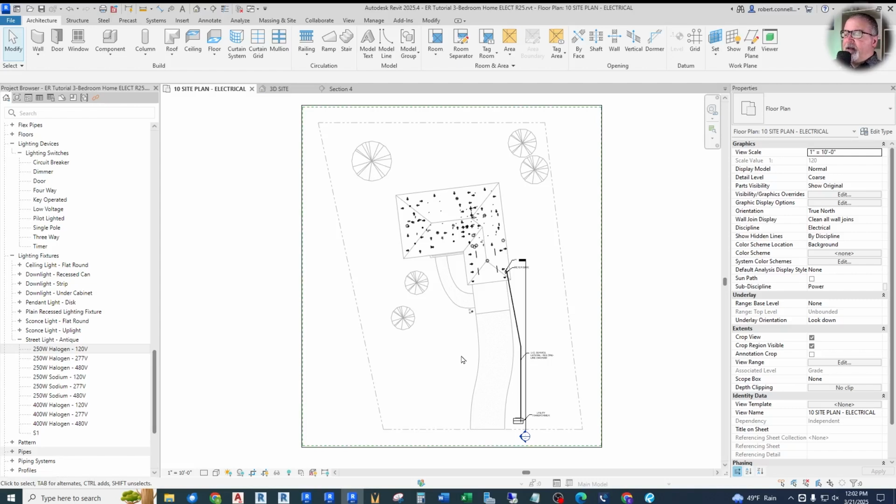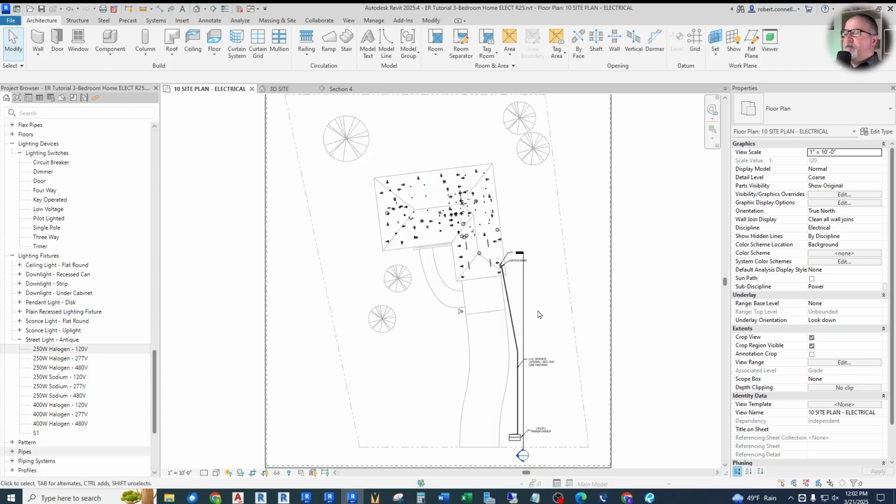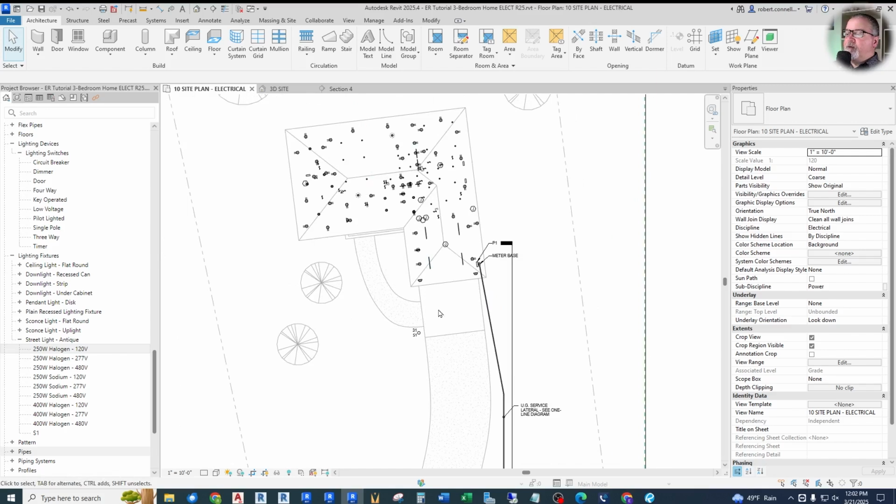Now to deal with this filtering issue. All right, hang in here with me. Filters are a little advanced, but they're very important, I feel, to learn even for a beginner. So once you learn these, you'll be glad you did. So the basic idea is the visibility is controlled by the categories. As we saw, we could turn those on and off. However, we have some things within the category that we want to stay on and some to go off. So how do we subcategorize things? Well, what we do is we set up a filter to look for some kind of identifier in, for example, in this case, for the site pieces that says leave that on, but turn things that don't say site off.